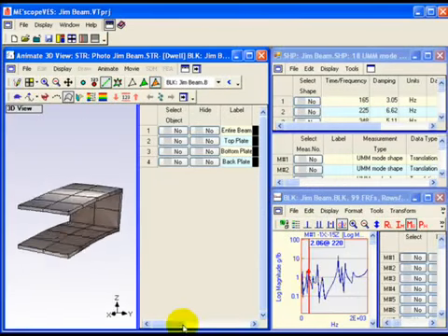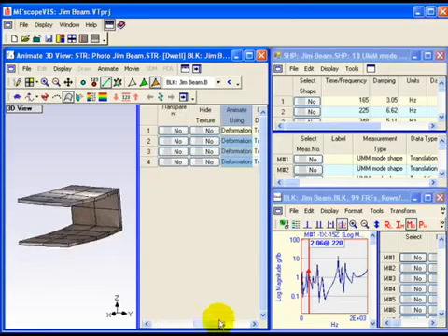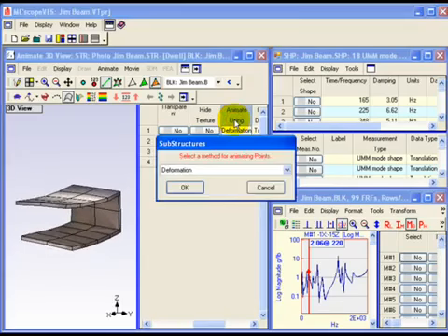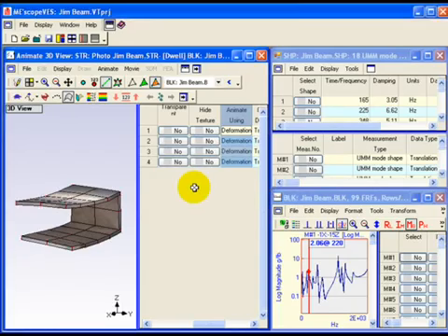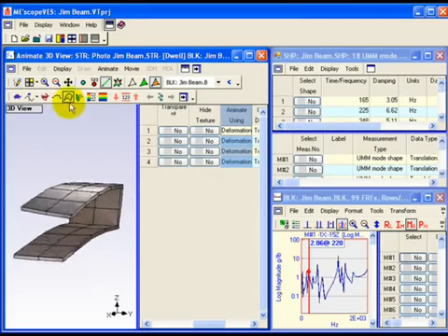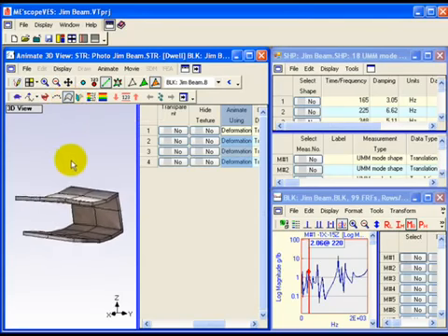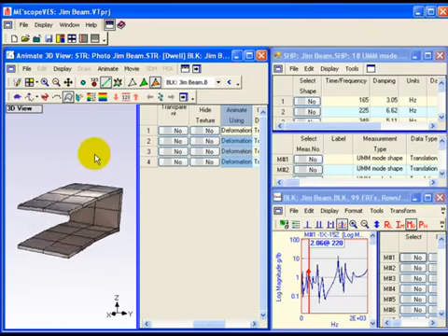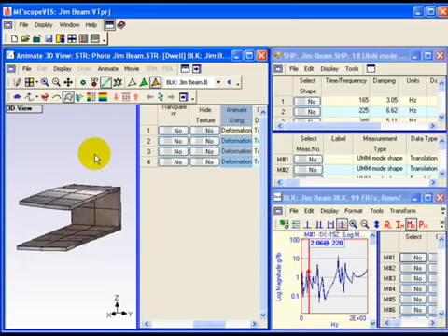Double-click on the Animate Using column in the substructure spreadsheet in the Structure window. A dialog box will open. Select Deformation or Both in the dialog box and click on OK. Execute Animate, Deformed to enable or disable the display of shapes as deformations at each point.